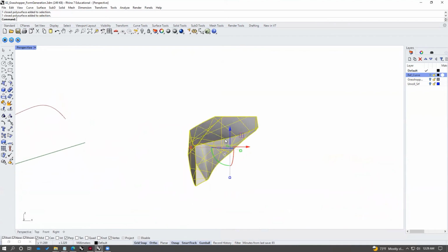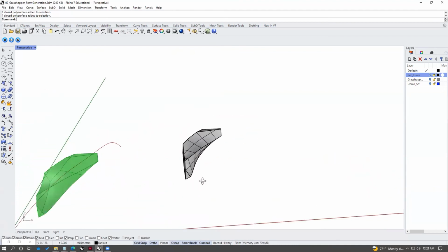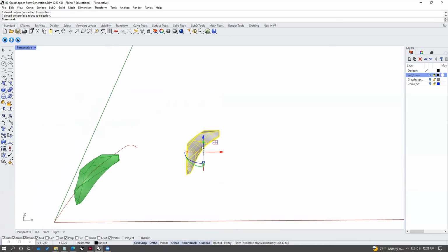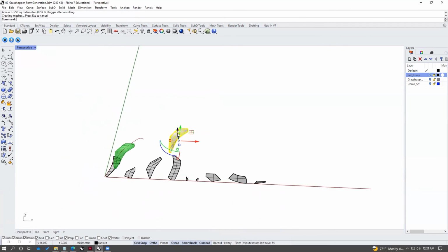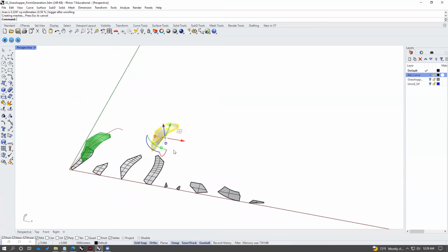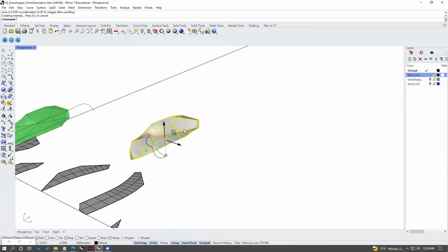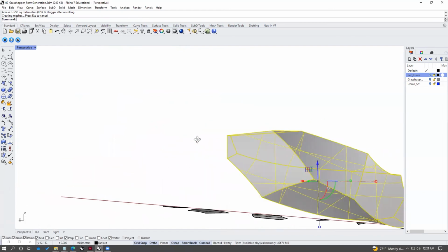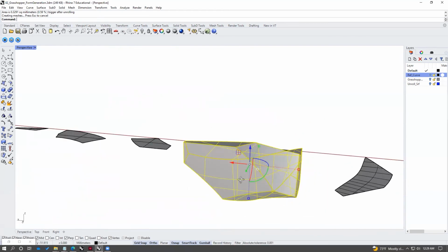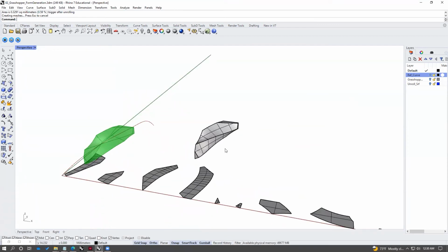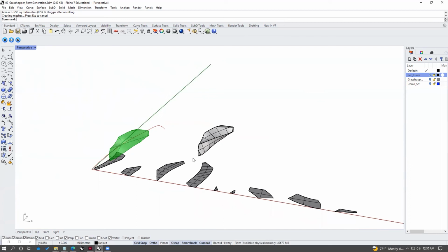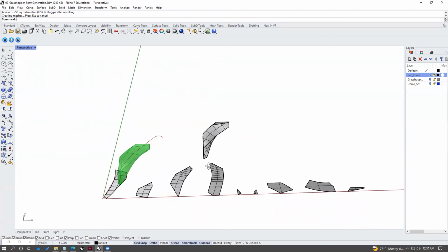So we know that this is going to be a singly curved geometry, which means that we can click on this and type unroll surface, enter, and we can unroll each of the panels of this object, which means we could cut these out of paper and make a paper model that would exactly represent this object. This is going to be really helpful for quick fabrication as needed in the program to supplement robotic fabrication.